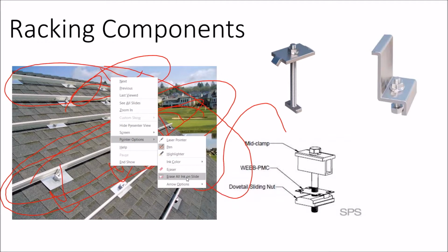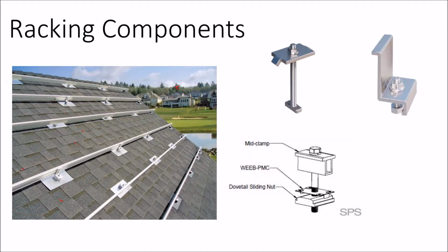And there's ways to get out of it. To ventilate the building, you could have a forced air ventilation system instead of passive. And so if you have a roof cap, if you have a vented roof, the ventilation may not matter so much. The fire code access may not matter so much. But what firemen are really concerned about is the additional weight on the rooftop, causing the building to collapse earlier than it otherwise would. And that's not just a solar problem. That's a tile rooftop problem and all these sorts of things.